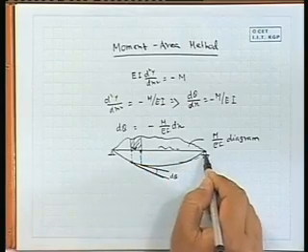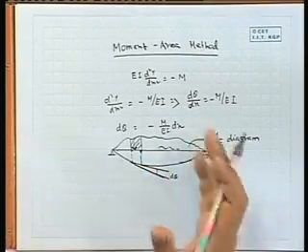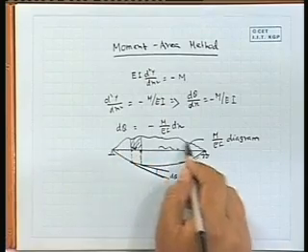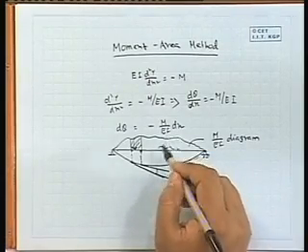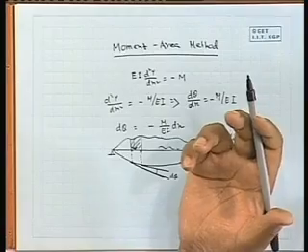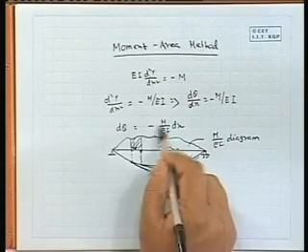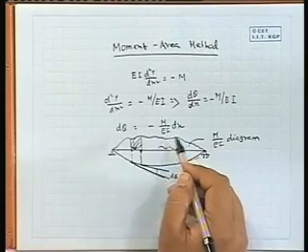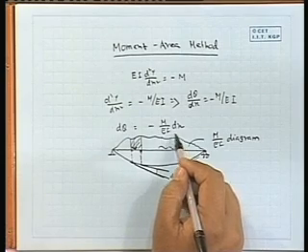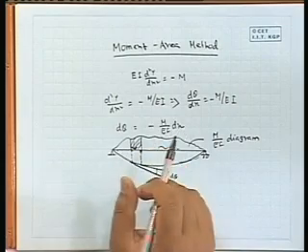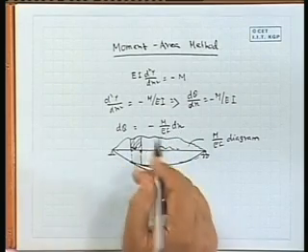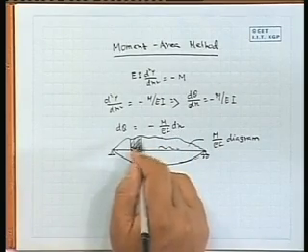Say some bending moment diagram divided by EI means we are basically representing the same diagram with some scaling factor. The scaling is 1 by EI. So, that diagram is the M by EI diagram. Say it is y, a function of x. So, M by EI is a variable quantity, a function of x into dx. This is a small increment, function of x into dx, and dx is very, very small, which means within that range we can assume this is more or less a uniform value.